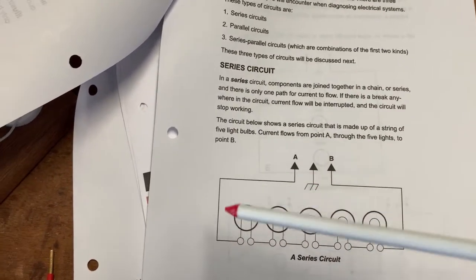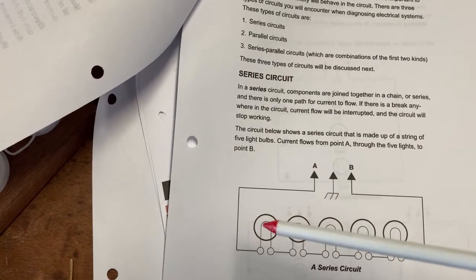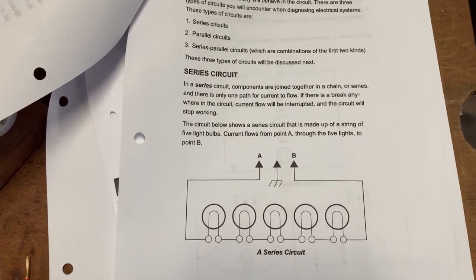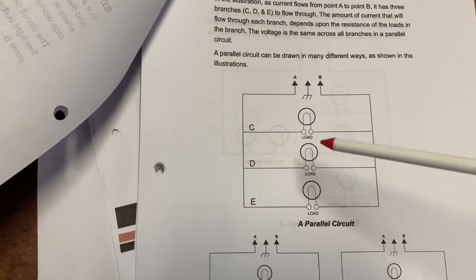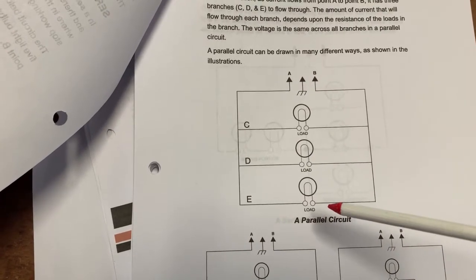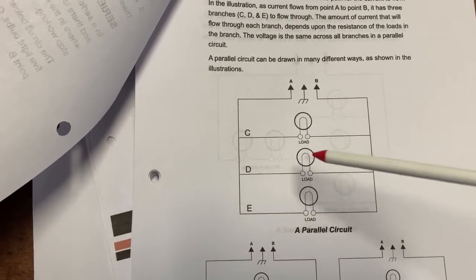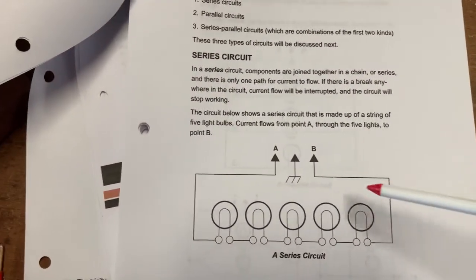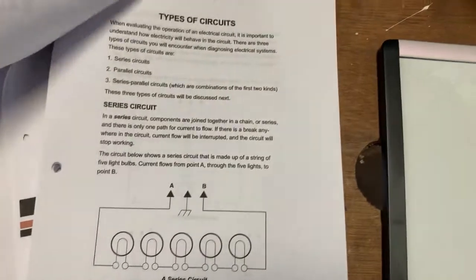Well, what happens is you get the combined resistance of all of these lights connected this way, so that they have to share the electricity, and they will be much dimmer than if this series were in parallel. In parallel, they each get their own individual amount of current and voltage, so that they will operate at full brightness from that connection. Whereas in series, since they are sharing the voltage and current, they will be dimmer. I'll show you an actual demonstration of that in a little mock-up we have here.